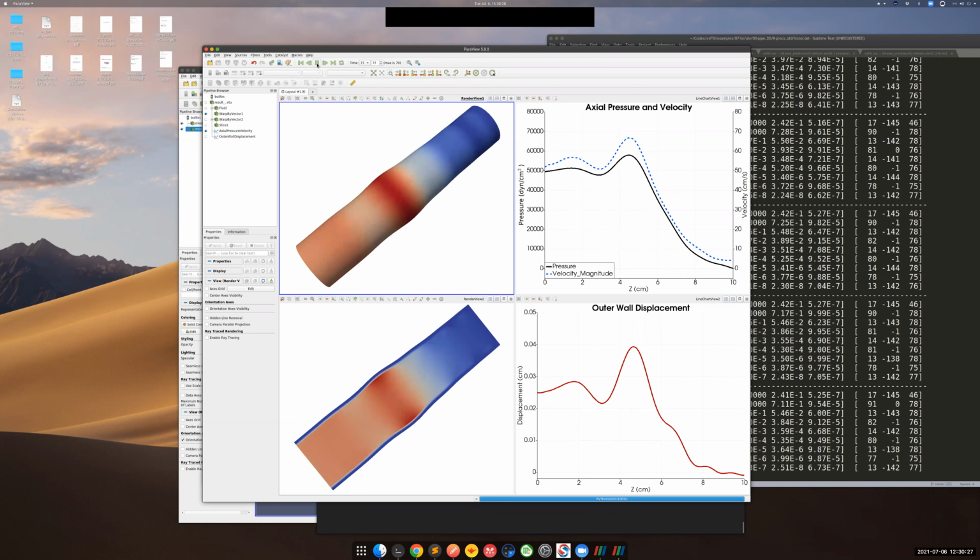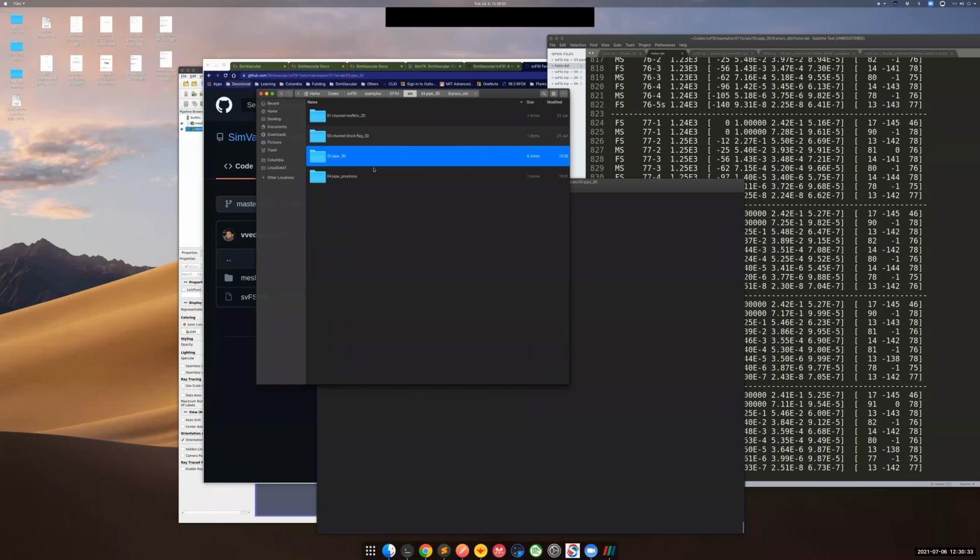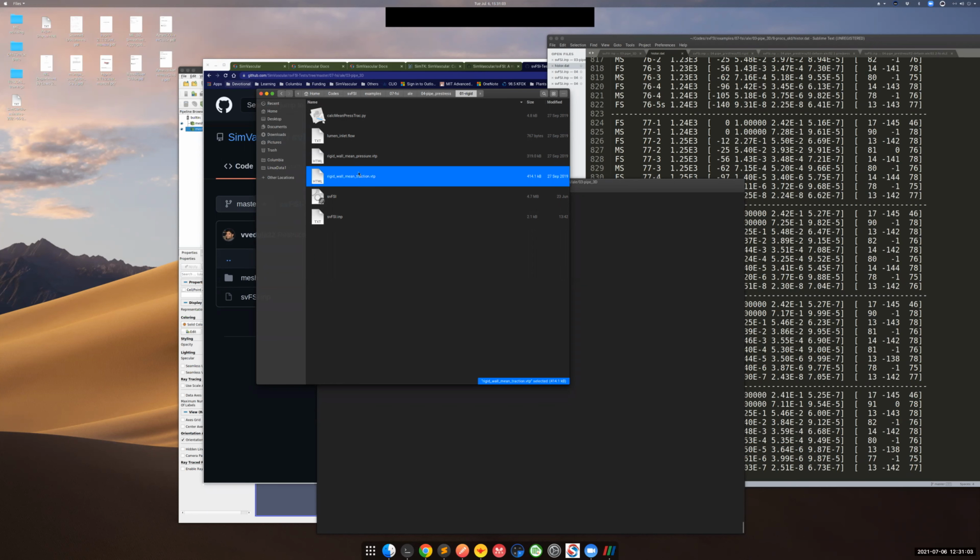Okay. So again, before closing this session, I just wanted to allude you to another quick thing. svFSI also allows you to do a pre-stress based simulation of FSI, which I will probably try to cover in the next video. It's very similar to the FSI that we just demonstrated. However, the pre-stress approach needs a proper workflow. What you have to do is first do a rigid wall simulation, just like how you do it for CMM based deformable wall simulations in SVSolver, and then you compute a rigid wall mean pressure or traction, and then go into the deformable wall simulation.